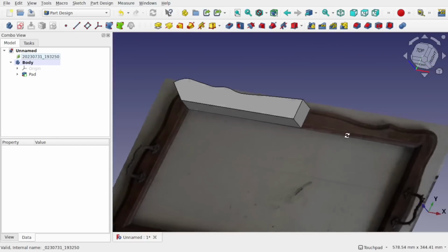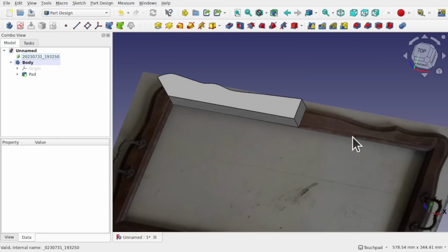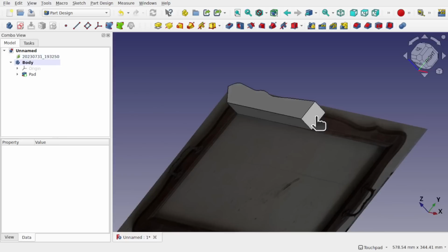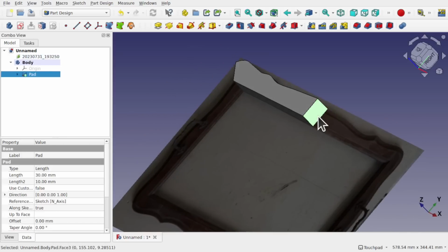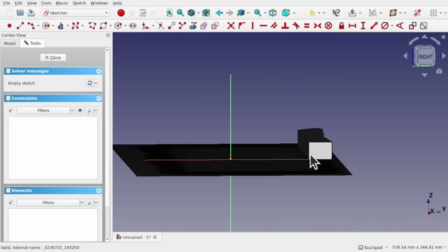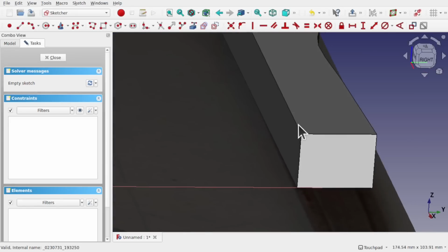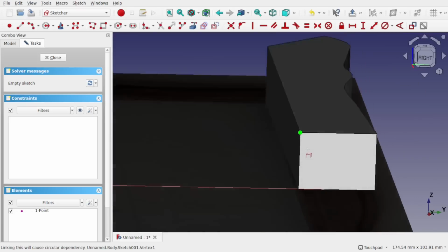So how do we do that? Well, we would use a subtractive pipe. We're going to hit one problem with this. What we'll do is use a subtractive pipe along here. Because we use symmetry, we've got this planar surface here. So I'm going to click that face, click once, just select that face. You see down here, the face has been selected, create new sketch. And we're going to attack this edge here. So I'm going to pull that edge in using the external geometry tool. And well, we just pull in this point here. So we've got something to attack there.